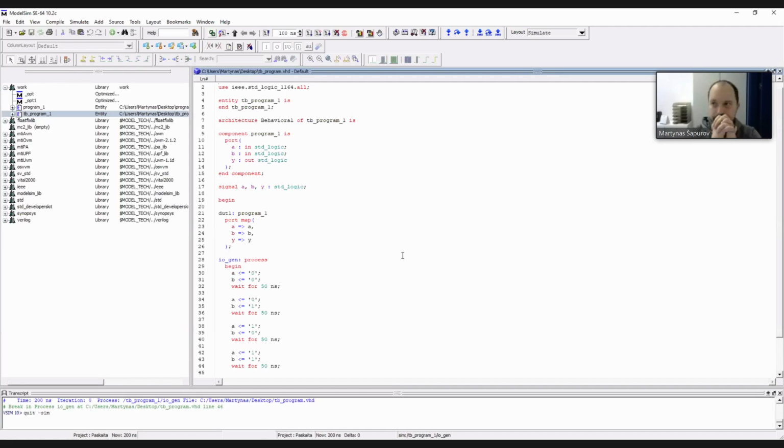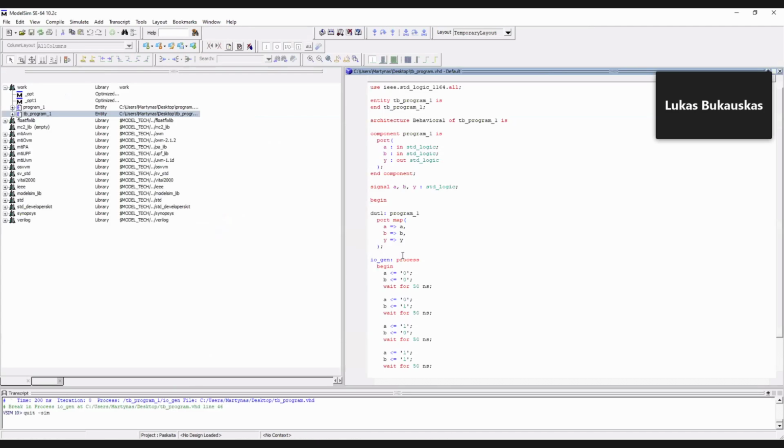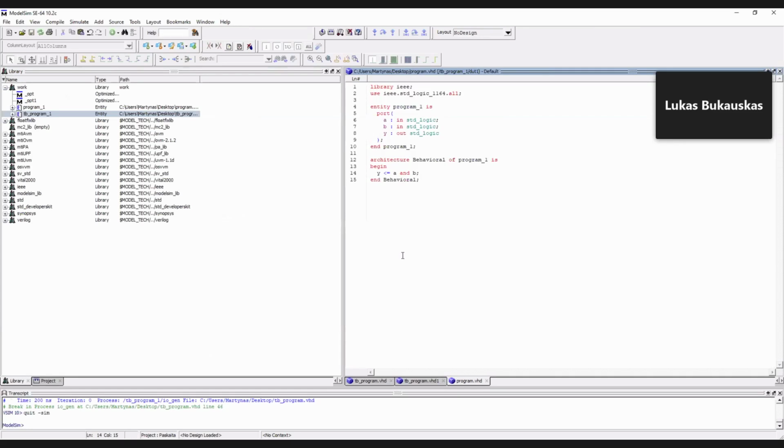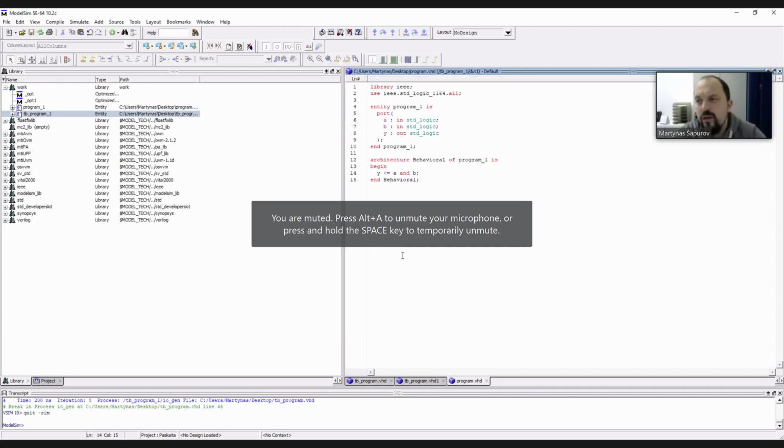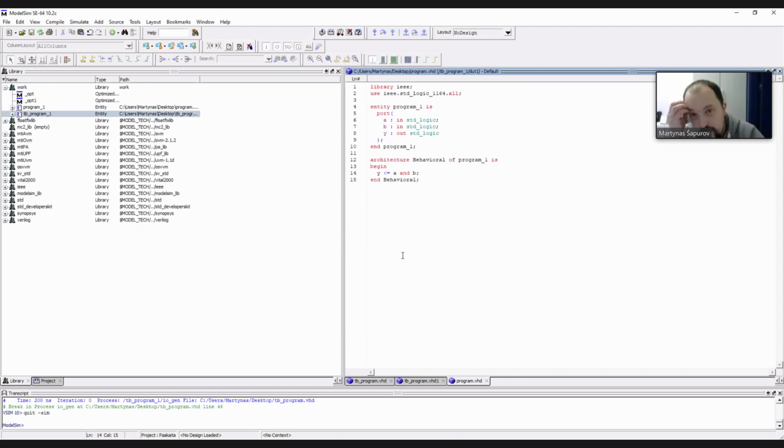All right. Questions? I tried doing the same as you did, but I'm getting an error loading design. So somewhere you probably made a mistake. It compiled everything correctly, but it doesn't simulate. It says that I should go to the website and update my version, even though it's the newest one. I think that usually problems occur when you have a very long path. This software doesn't like long paths at all. It likes when the path is short, directly on the C drive somewhere. Okay, I'll check.